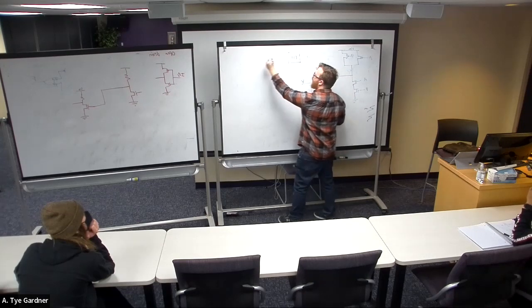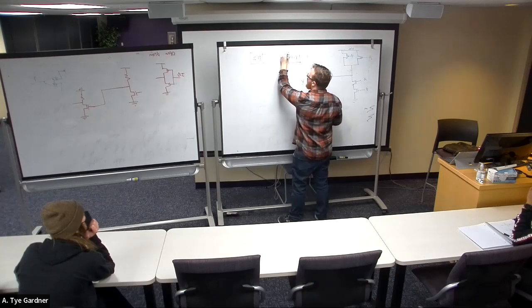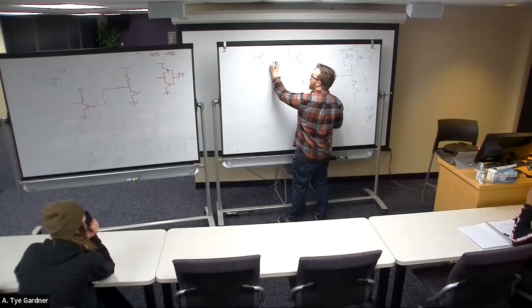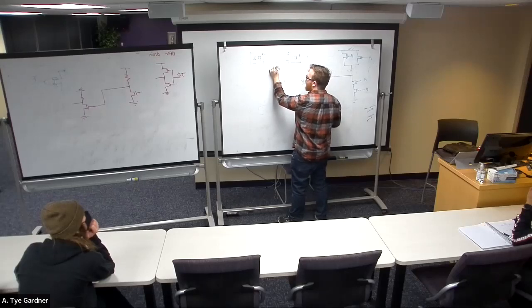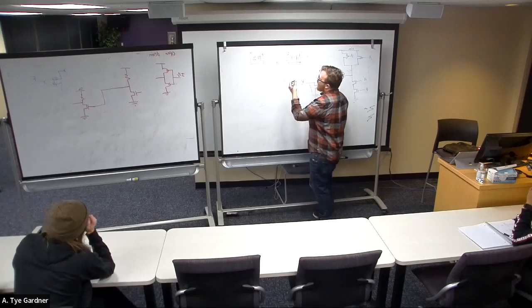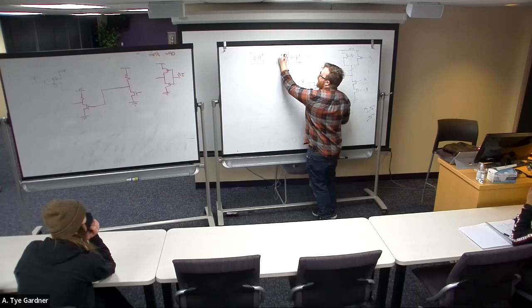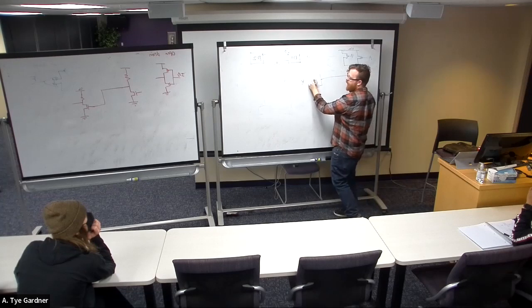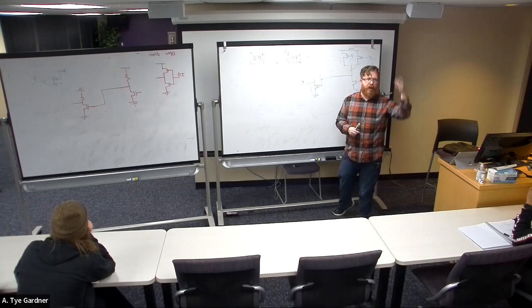we'll call it D1 and D2, and they have a 2-wire communication system. Well, then what that means is either one of them, in fact, we can even do it outside, just needs a pull-up resistor, right? Because if I add a pull-up resistor, then I'm back to the circuit that I drew first, right? And it will pull up to 1.